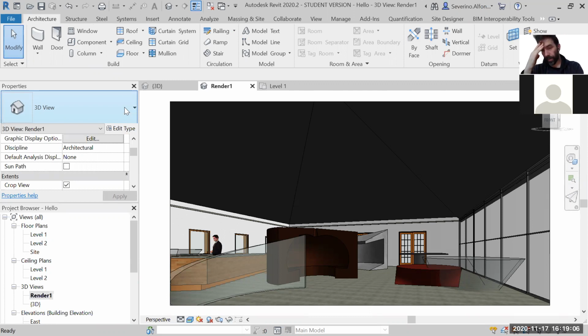You can add multiple things. You can add an extrusion to a blend, to a sweep, et cetera, et cetera. So it doesn't have to be that one creates the furniture and that's it. You can add voids if you need them. They're great for, again, those little weird things that are not necessarily standard in Revit. And they work pretty nice.